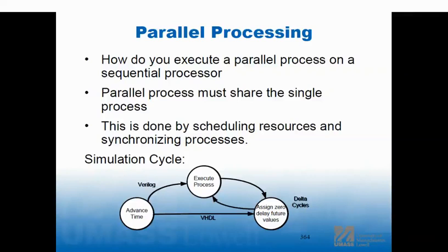You occasionally see delta time. If you look at a list file in ModelSim, it'll show you the delta time. And if I see big numbers, if I see a delta time of 10, I bet I have a path in there that has too much logic in it. I don't do this as a hobby, but if it catches my eye, I'll do something. When am I going to find it? I find it in synthesis, when I can't make timing on it. But the reality is, when I see it in the list file, something's wrong, right?